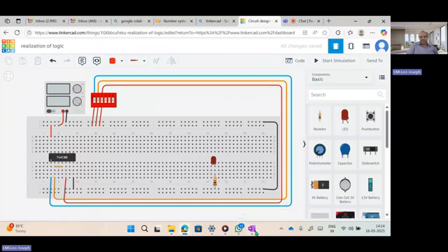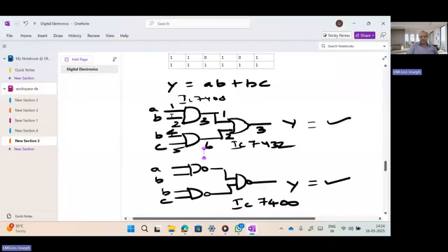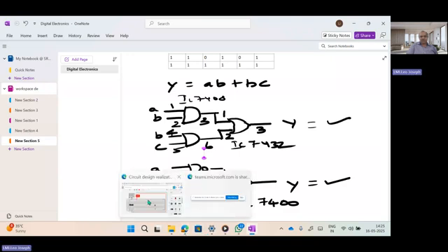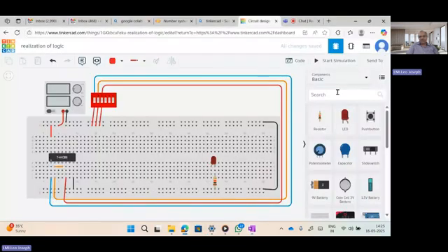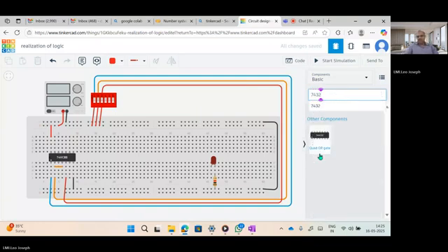You can just cross check what I am doing. The first pin is a separate input, the second pin is also from a switch. The second and fourth pin I am shorting. The fifth pin is a direct input, that is nothing but from the switch. So the third and sixth pin we have to give to IC 7432. How to do that, let us check. So here I will type the part called 7432. It is an OR gate, so I have to connect this here.